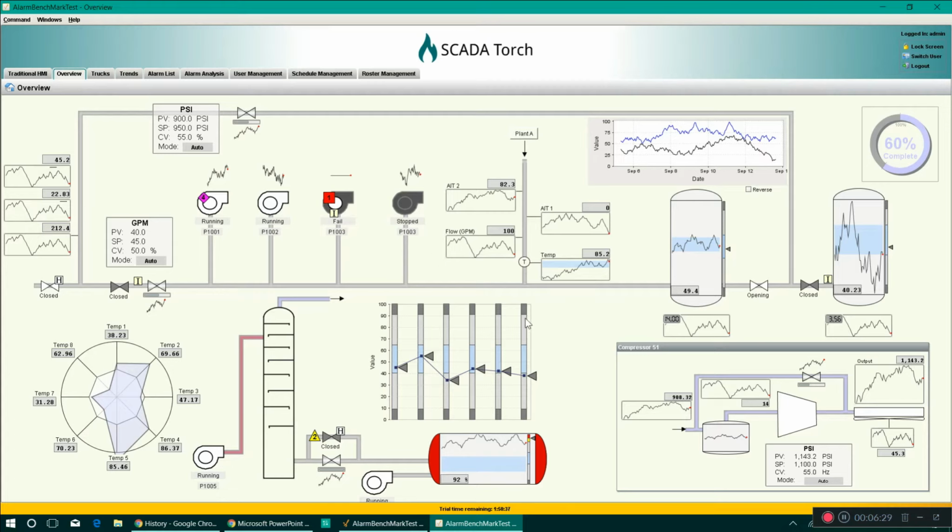I chose not to have any animation on the screen. You can certainly use blinking animation for critical alarms, things of that nature, but we should definitely stay away from using animation for normal operating states, like things that are running.